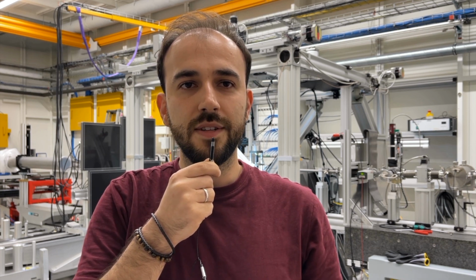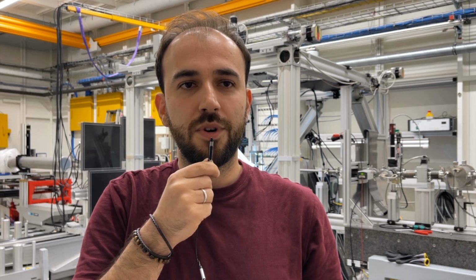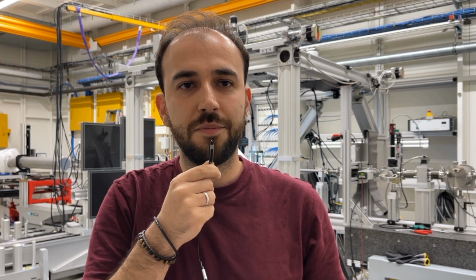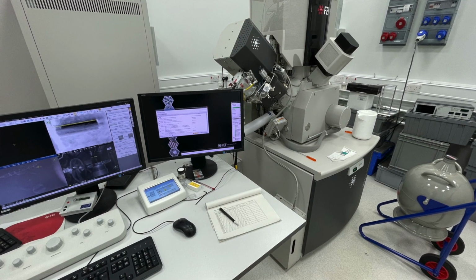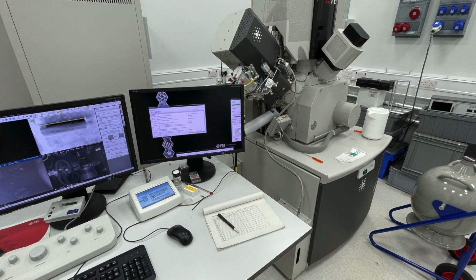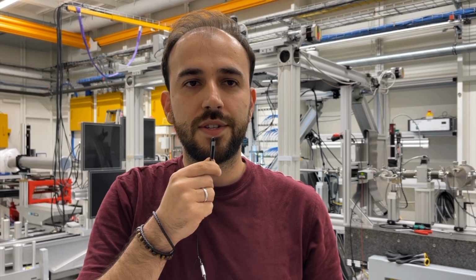Lastly, proton irradiation depth-dependent damage behavior was once again exploited to compare the dislocation density measurements from XRD and STEM. This was achieved by utilizing our PFIB microscope with its cryostage temperature capability. Large FIB foils in the range between 40 to 50 microns were prepared to image the entire proton irradiated region on the same samples and on the same surfaces where the XRD measurements were carried out.